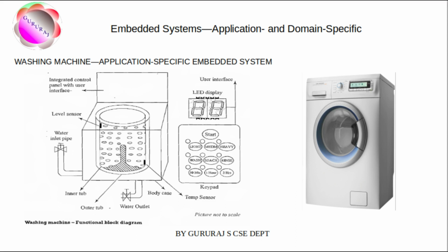The actuator part of the washing machine consists of a motorized agitator, tumble tub, water drawing pump and inlet valve to control the flow of water into the unit. The sensor part consists of a water temperature sensor, level sensor, etc. The control part contains a microprocessor or controller based board with interfaces to the sensors and actuators. The sensor data is fed back to the control unit and the control unit generates the necessary actuator output.